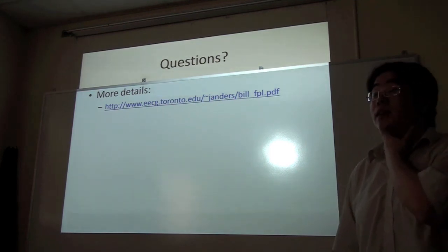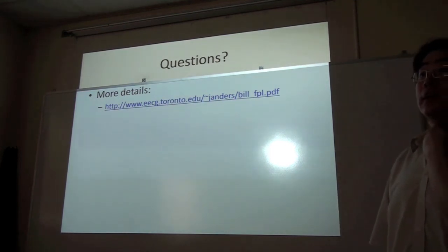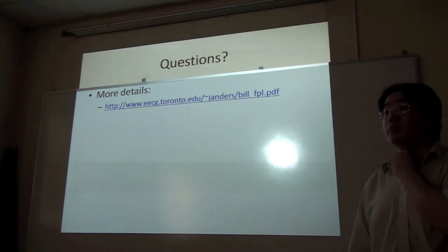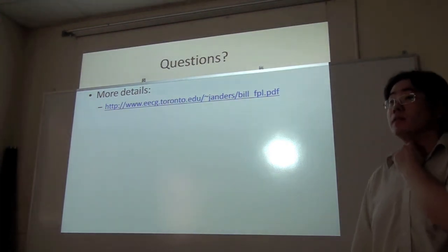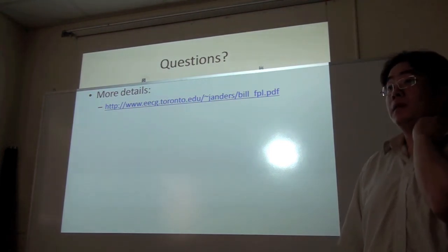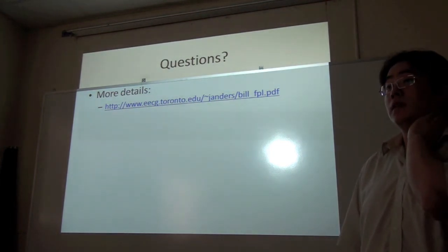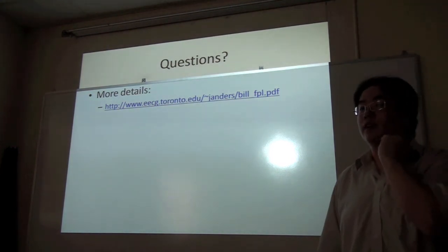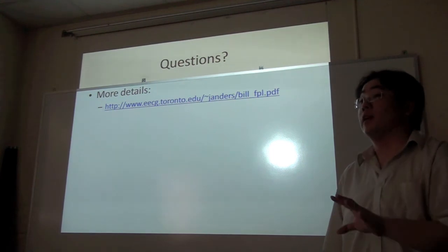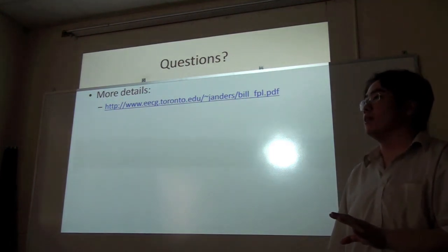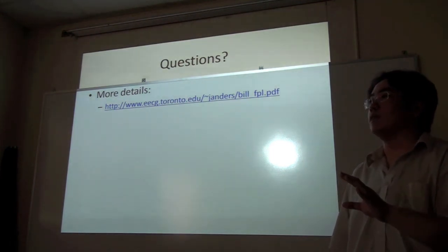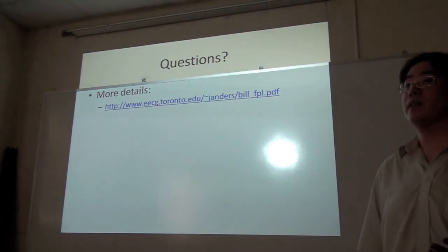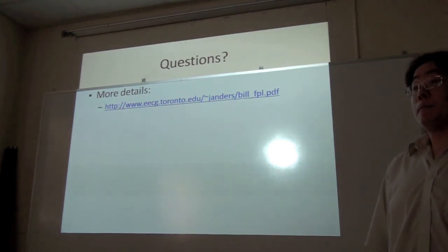The other thing I was going to ask about was modeling, or looking at designs with more than one clock, and addressing the fact that you have a limited number of clock networks in the device. Right. And those restrictions will affect how well you can bring all these clocks together. Yeah, that's right. The problem is that VPR is done only in the single clock scenario, and for us even to test it, we need to have VPR support multiple clocks. Yeah, I recognize it's a limitation.